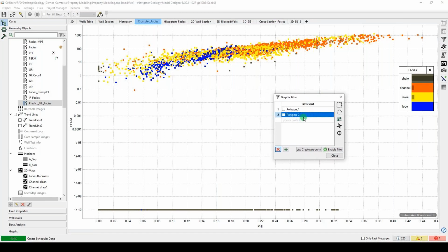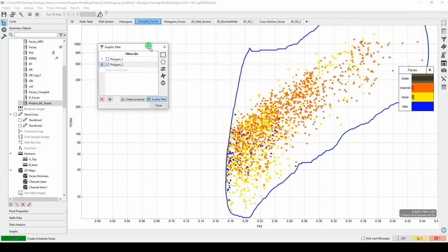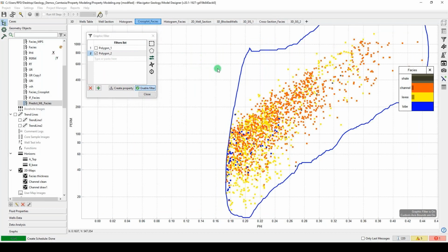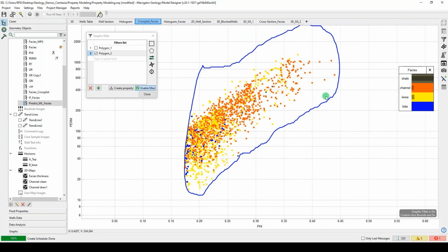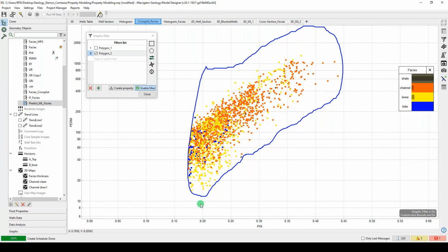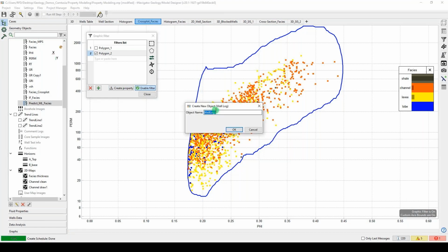The first place we're going to start, and we're going to create a Facies from, is our cross plot window. So I've created a polygon earlier around some of our higher poroperm data. Best to note that I've got porosity and permeability displayed here, and I've color filled by our Facies template that we predefined. And you can see now what I've done is filtered out the data that I haven't drawn a polygon around. So I've encaptured this, and we've got our higher porosity and permeability that might be our channel-bearing or sand-bearing reservoir here. What I want to do is create a property from this. The property that I'll create is a Boolean log.